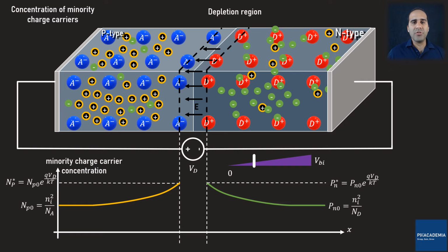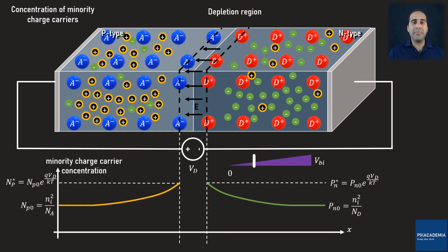What you need to pay attention to is the metallic contact connected to the right end of the N semiconductor. This plate has an electrical connection to the negative terminal of Vd, and it has lots of free electrons. Once the recombination happens, new free electrons enter the N semiconductor. At the same time, holes are still diffusing into the N semiconductor, and therefore the process that I just talked about continues.